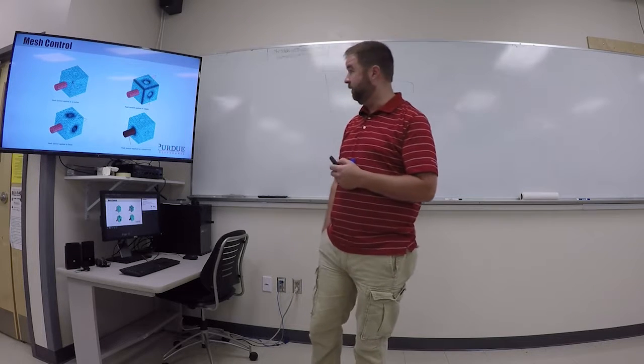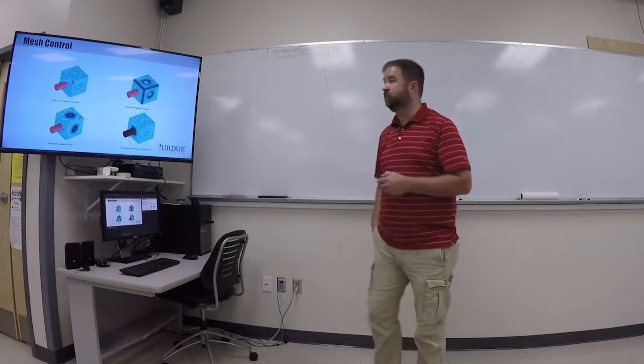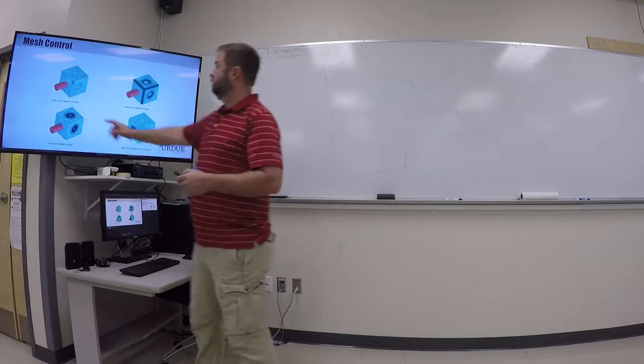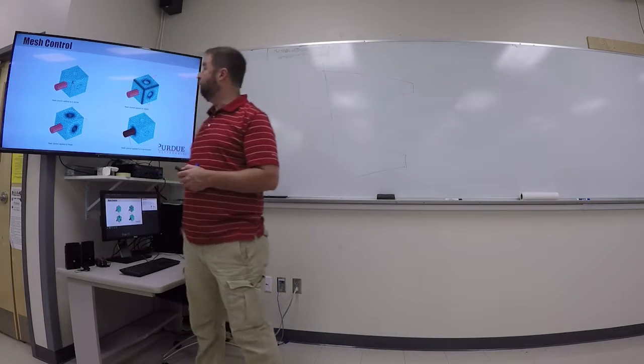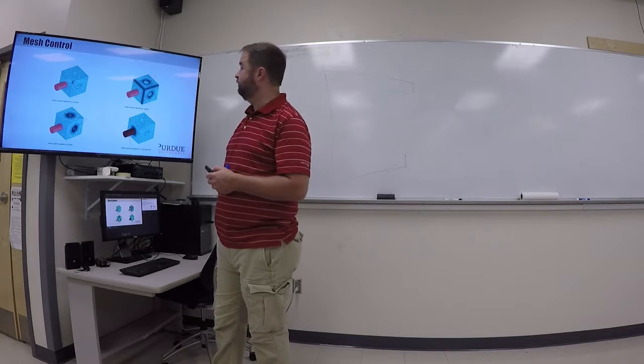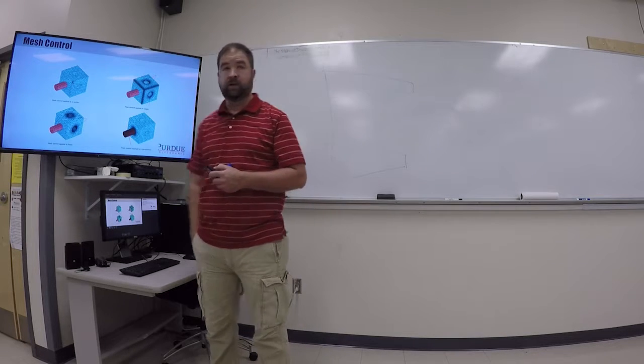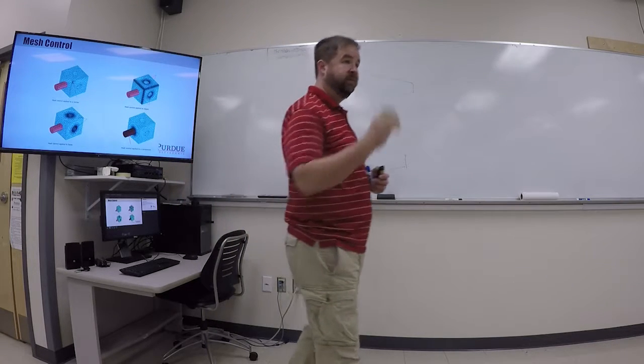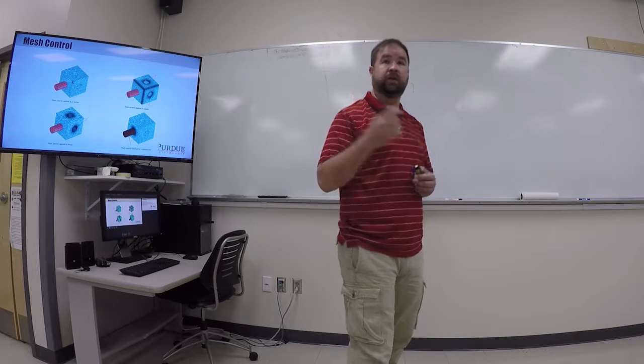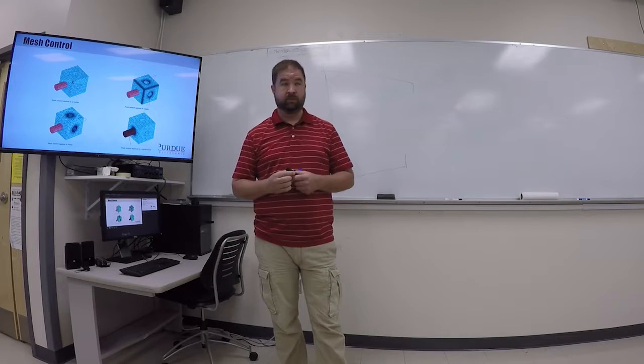Okay, I couldn't remember if I had a picture of that or not. Okay, so if this is my model, and I find that I have some high stresses in certain areas of the model, I would like for the mesh to be smaller in the areas of high stress.